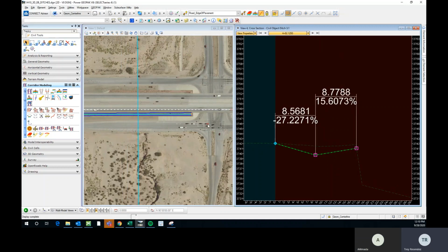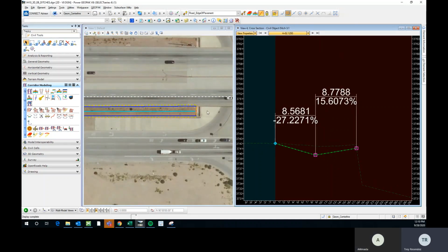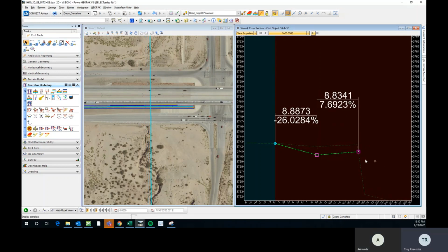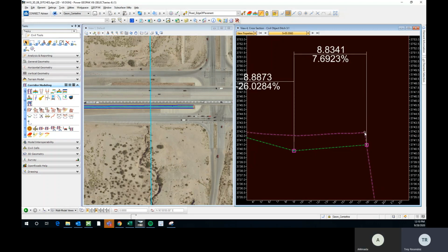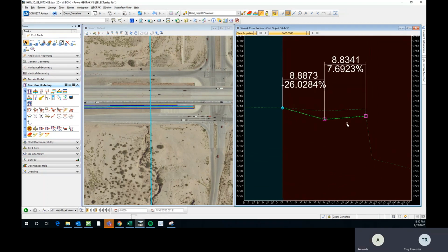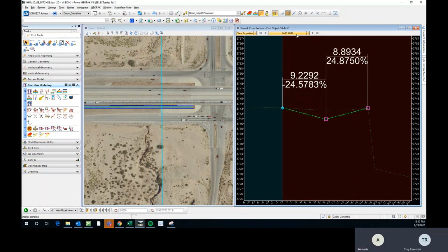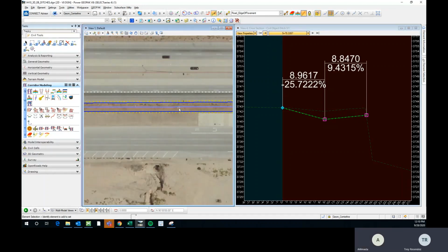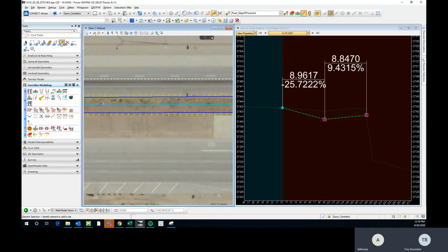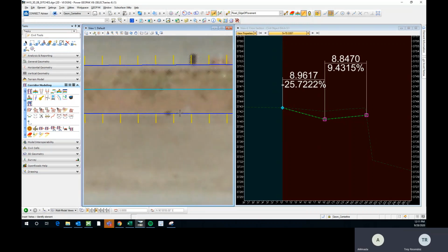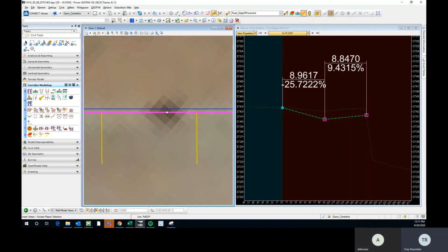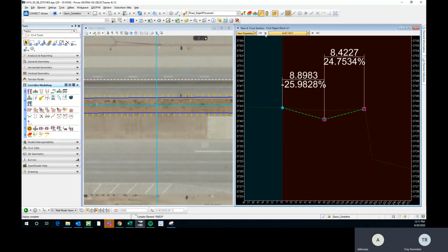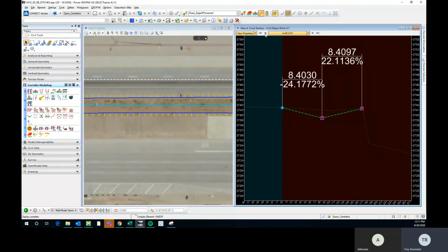So this is really the same workflow to do for the rest of the ditches. It's really the same thing for the rest. So maybe in this case I would adjust the horizontal a little bit because we're kind of missing out here. Is there an easy way to move it? Or do you have to move it in the horizontal? Well, in this case, I would probably just add a vertex here. So if you come to 7 and then go insert vertex, then we can, I think it's like around here, we can just move this a little bit right inside. Okay. And this can be referenced to the alignment if you wanted to, but you see how now it's inside that ditch area. Yeah.